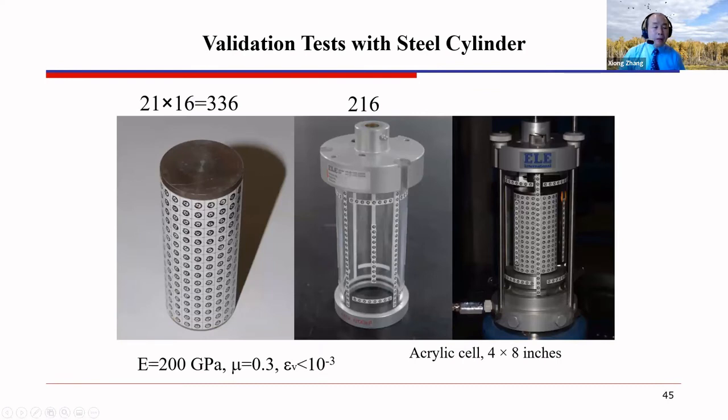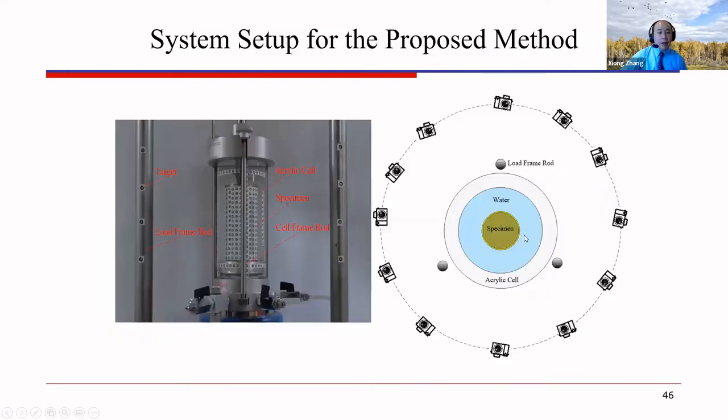We used a rigid stainless steel cylinder as a soil specimen. We put it into the cell, filled it with water, and ran tests at different confining pressures.